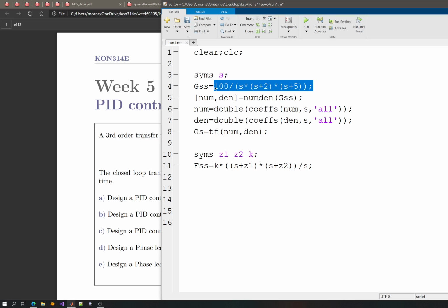So basically, your pole zero cancellation is restricted to the left-hand side. And thinking about that, I can say that maybe I can choose a zero here at 2. Also, I can go ahead and choose another one at 5.